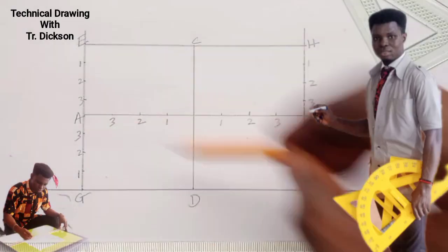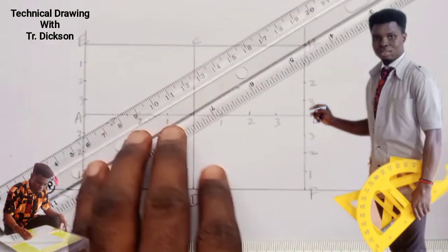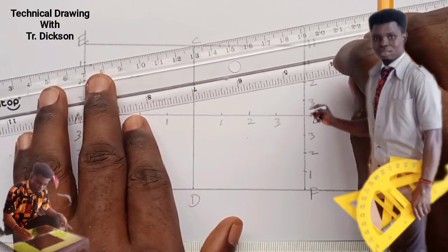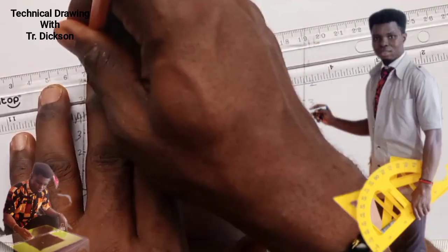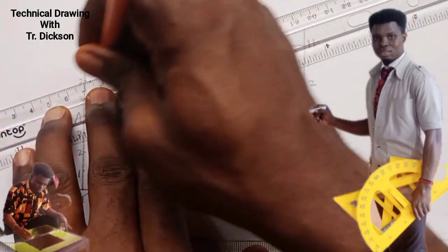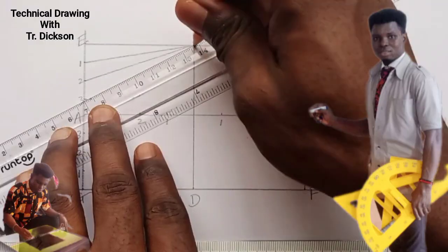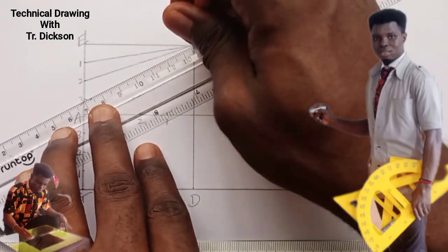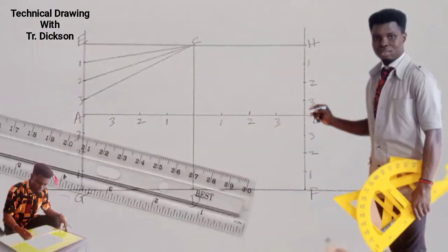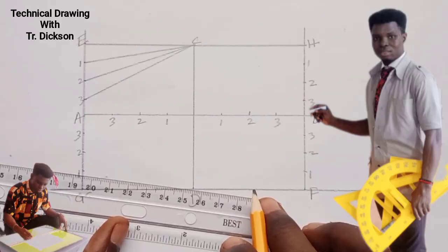Now I'm going to radiate lines like this, this, and this to start making my ellipse. So let's see how that goes. So that means 1, ensuring that it is at the exact point of intersection. Right, now I come down to make the same thing using my ruler now, with the T-square and set square for now.